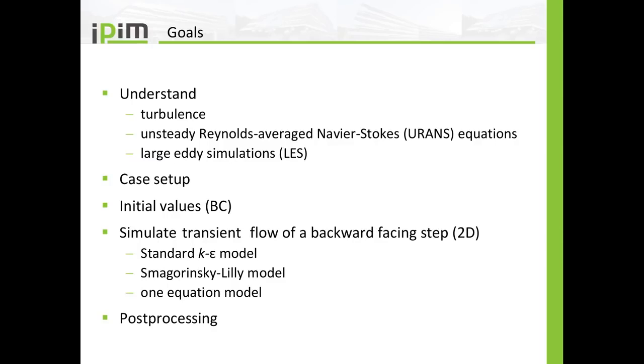I'm going to run three transient simulations of a backward facing step, which is a two-dimensional simulation, and I'm going to use three models: the standard K epsilon model, which is a Reynolds averaged model, and the Smagorinsky-Lilly model, and a one equation model, which are large eddy models.